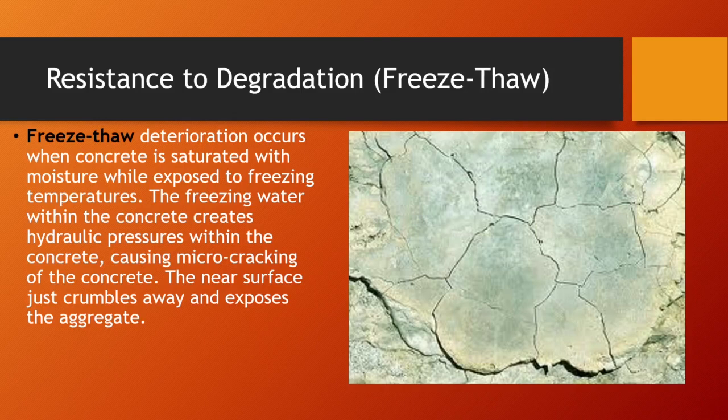Effectively what happens is, when you pour concrete, you need to vibrate it with these vibrating pokers. So you'll see the guys standing there dipping these long pokers into the concrete, and they're trying to vibrate all the air pockets out. And if it's poorly done, when air pockets are exposed to rain, to water, of course, especially in winter time, the water freezes and expands, and then it starts to break down the concrete around it.